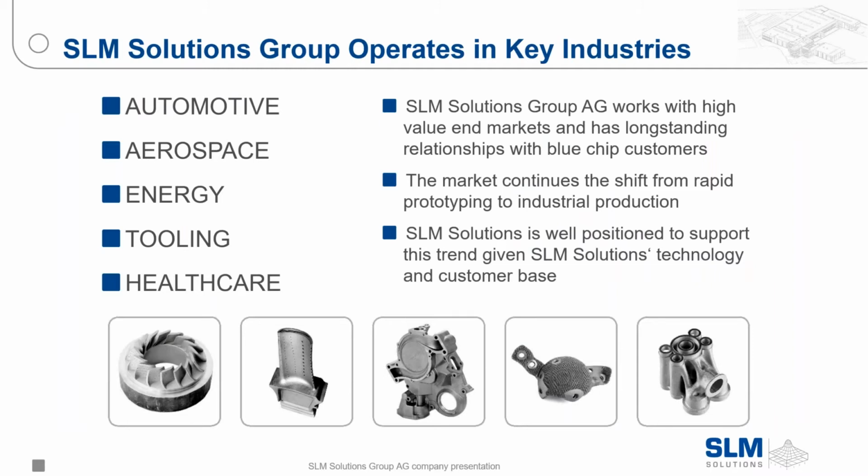These are the 3 machines that we provide right now. SLM 125, as the name suggests, is a 125 millimeter cube. It has a single 400-watt optic in it. And then we have the SLM 280 2.0. This is an improvement of the original SLM 280. It's got a 280 by 280 by 365 build envelope. You can get that with either a single optic or a twin optic.